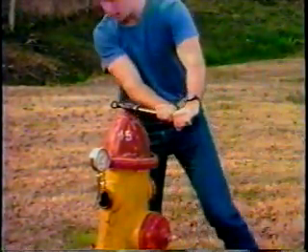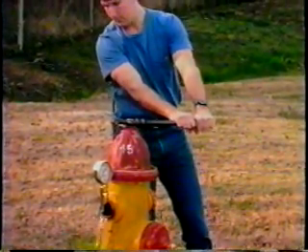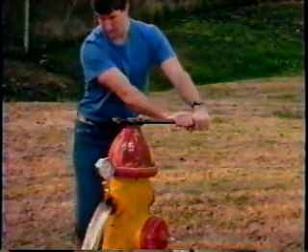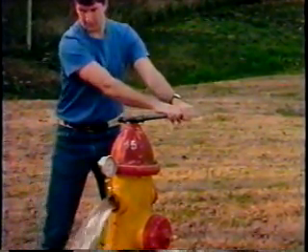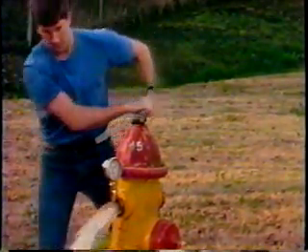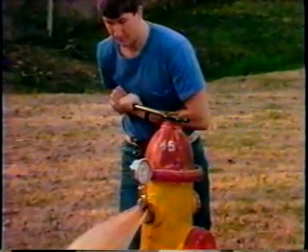The person at the residual hydrant needs to control the test because in some cases you may have several individuals opening hydrants and you don't want them to be opening them simultaneously. Instead, you'd want the hydrants to come online one at a time. And the individual at the residual hydrant is in the best position to decide when it's time to open up another hydrant.